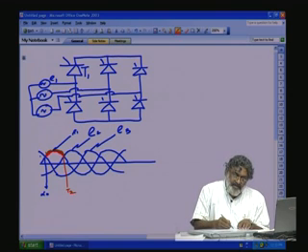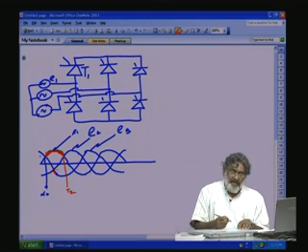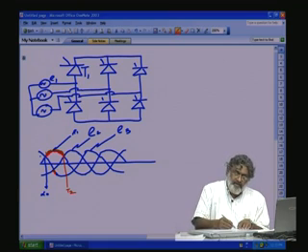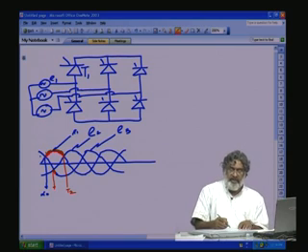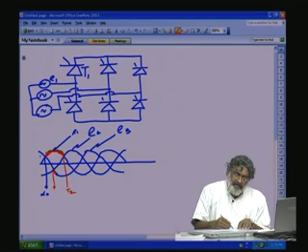But if you see the negative side, that is this portion, here E3 is more negative. So, for each phase whether positive or negative limb, at the same firing angle alpha equal to 0, we have to use for the positive or for negative. For positive, alpha is the firing angle here, for negative the firing angle alpha starts from here, okay. From there the phase becomes maximum negative. Here the maximum negative will be E3. So, here the T2 thyristor will be conducting. This is T2.